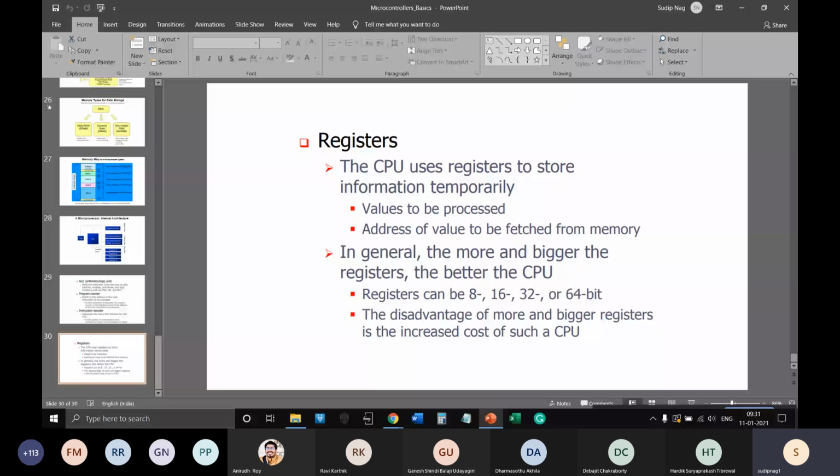See, in digital circuits, we use MOSFETs or BJT transistors. Typically, we will consider only MOSFETs. Those MOSFETs are used in either cutoff or saturation. They are not used in the triode region, typically, in digital MOSFET circuits. But for ultra low power operation, people are exploiting the triode region. Triode is actually typically used for analog circuits, where there is a linear V-I relationship, and that linear relationship is exploited.